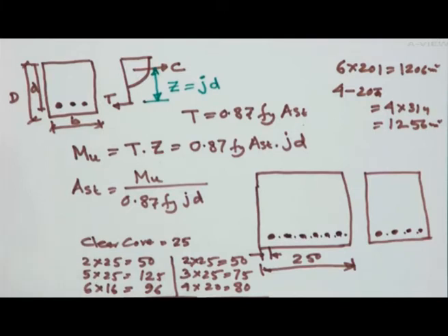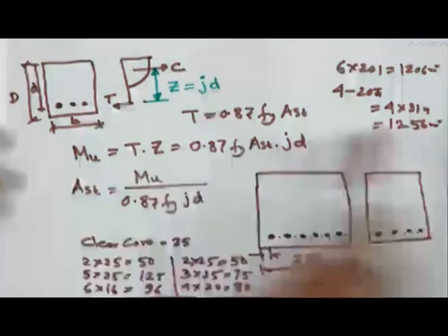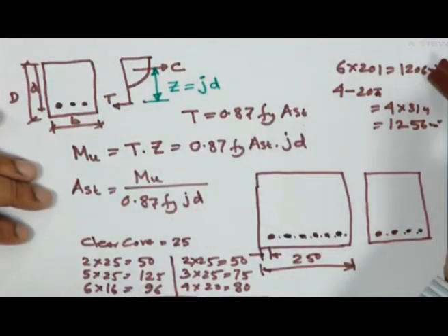So that's why at site, based on experience or from the design office, they find out how many tons of 8 millimeter dia bar they will procure, how many of 12 millimeter, 10 millimeter, and likewise 16, 20, 25. Now at site, even if the drawing shows a particular diameter, they will do an equivalent, that means 6 into 201 means 1206.